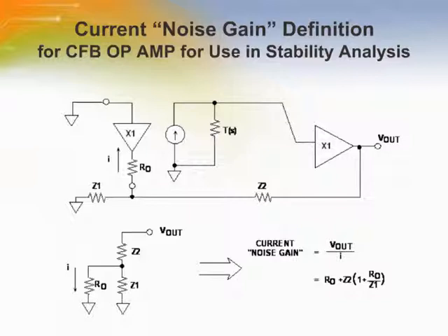The CFB op-amp is normally optimized for best performance by a fixed feedback resistor R2. Additional poles in the transimpedance gain occur at frequencies above the closed-loop bandwidth FCL set by R2. Note that the intersection of the CFB current noise gain with the open loop occurs where the slope of the T sub S function is 12 dB per octave. This indicates instability and the possibility of oscillation.